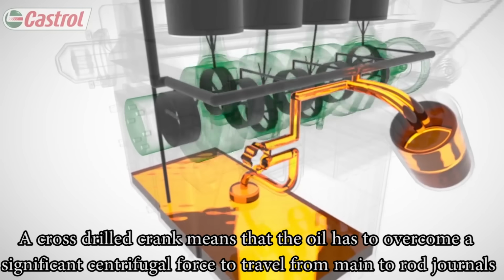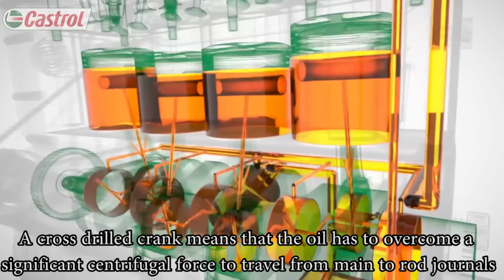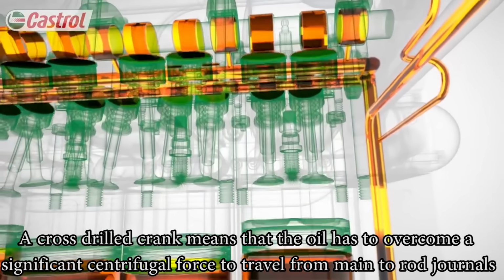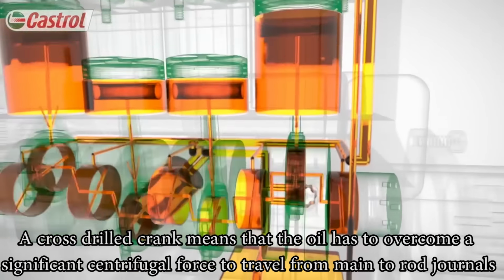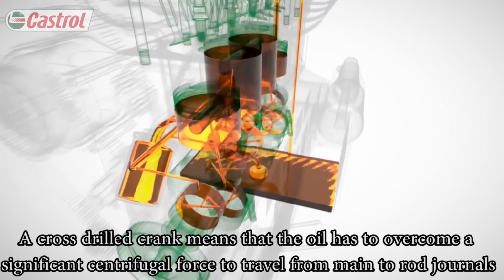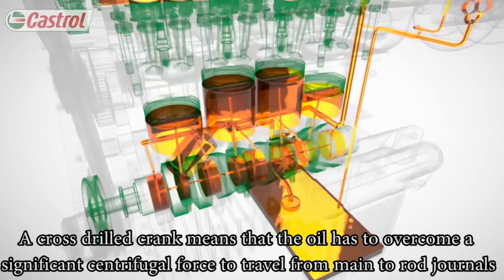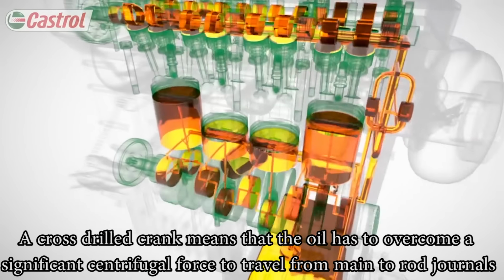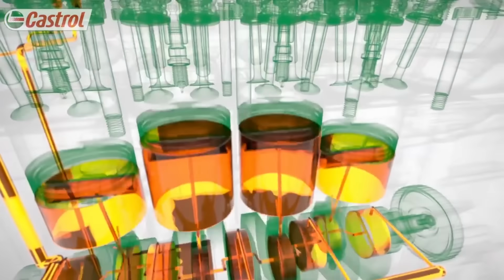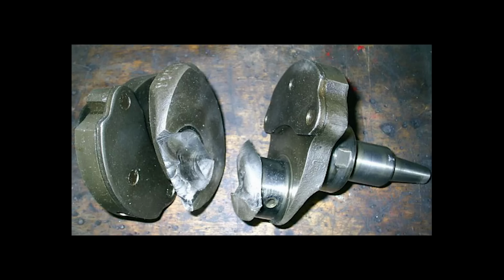Now, straight shot oiling is seen as a superior crankshaft lubrication according to some. And this is because in a cross-drilled crankshaft, pressurized oil must enter the main journal and overcome the centrifugal force of rapid acceleration or RPM to reach the center of the crank before the oil can travel to the throw, i.e. the rod journal. Now, increased oil pressure is often used to overcome this centrifugal force, but in extreme applications, enough pressure sometimes cannot be generated, and this can result in engine failure.